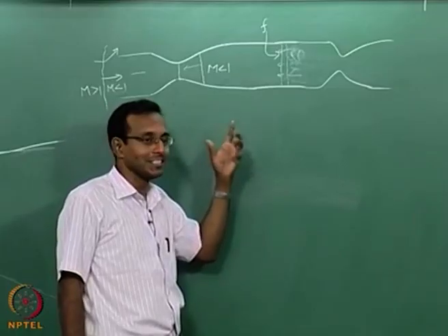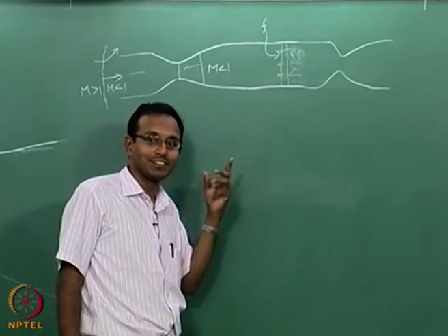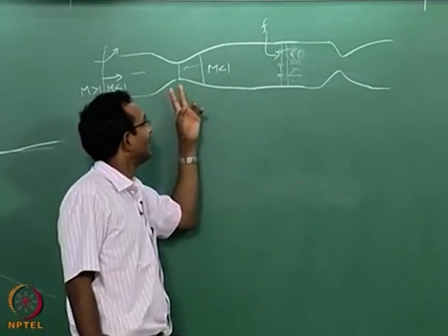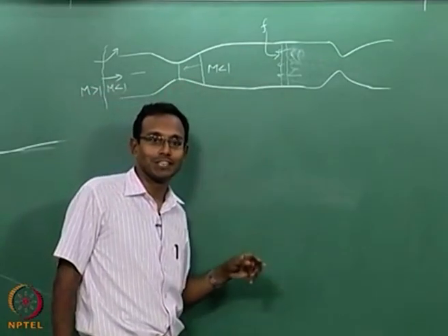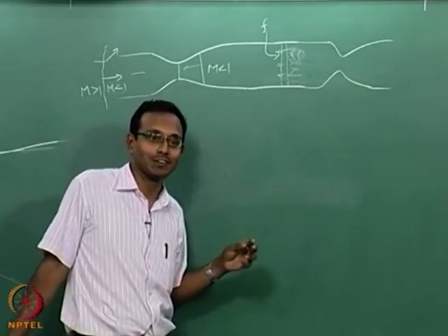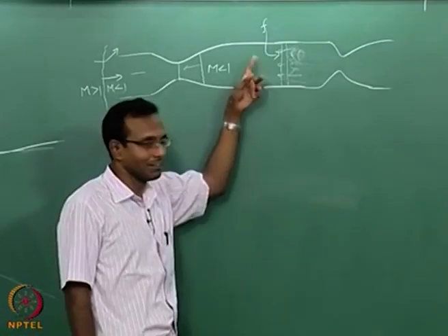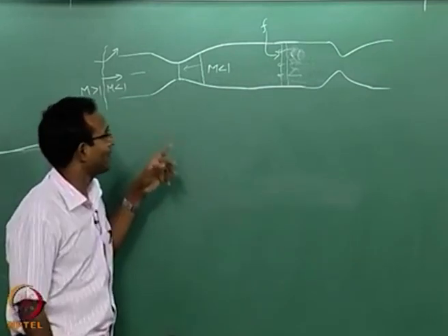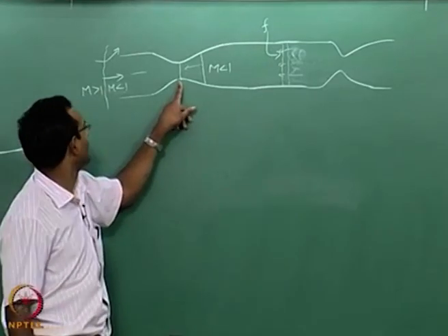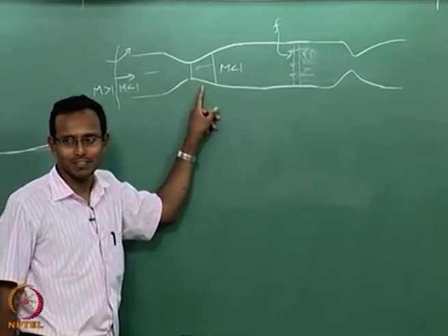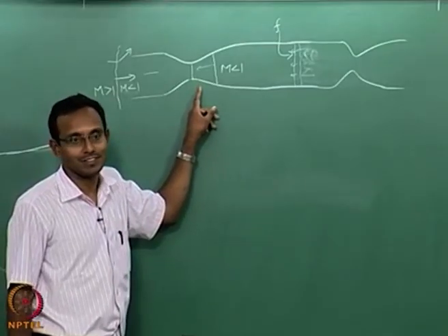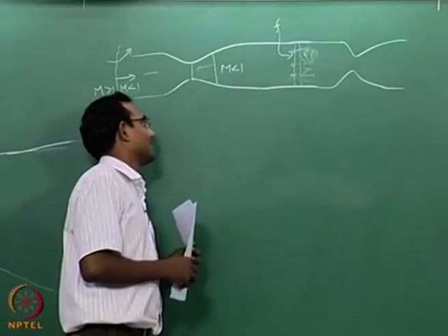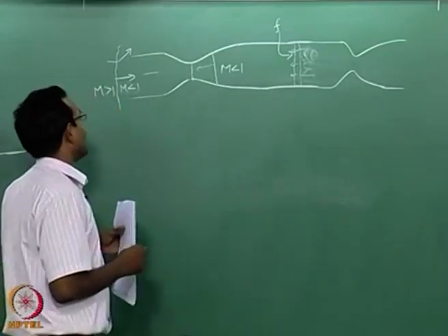Heat release increase causes increase in pressure. Increase in pressure causes a wave to go up. That whole sequence causes a coupling, and that causes acoustic instability, thermoacoustic instability they call it, because it is linked with the combustion also. If such a thing happens, then there is a possibility of, if I am working on the edge, the shock jumping out, coming back, jumping out, coming back. Typically nobody works in that region. Typically people work safe on the inside. That is one thing you have to think about.